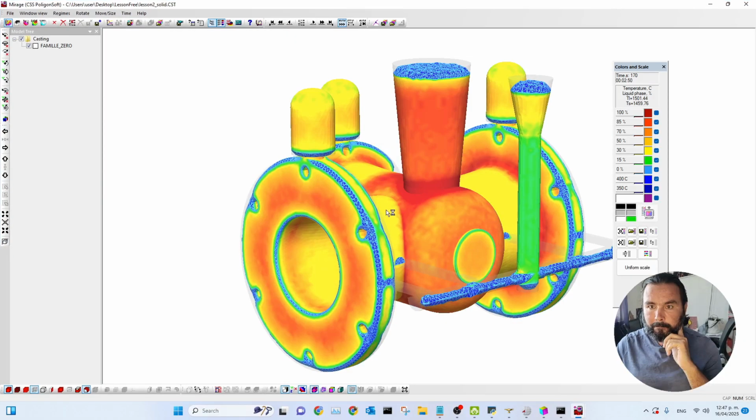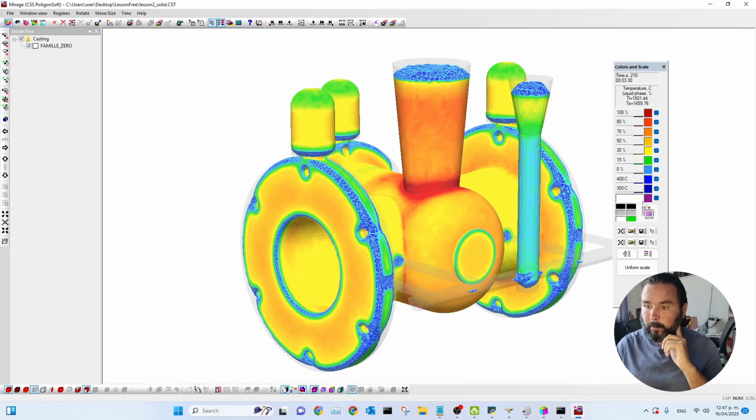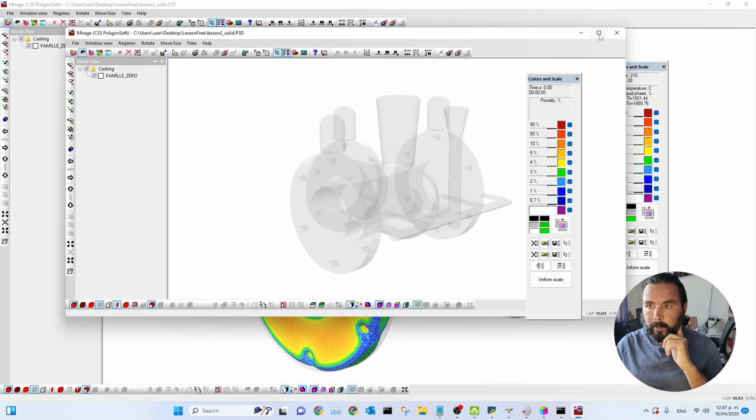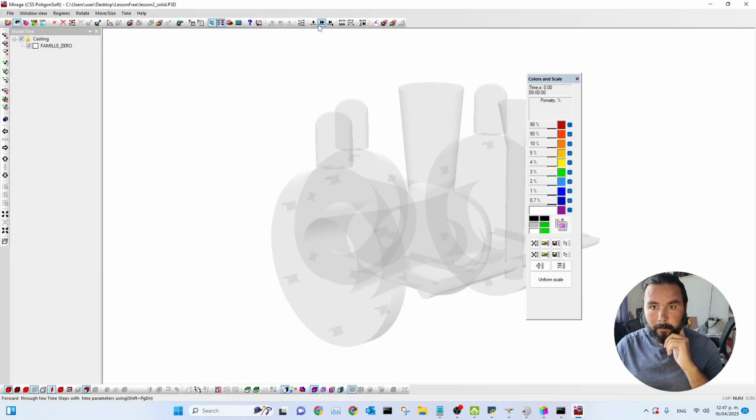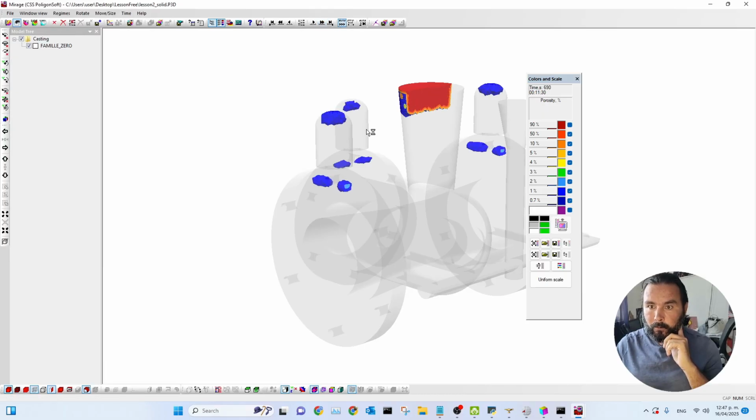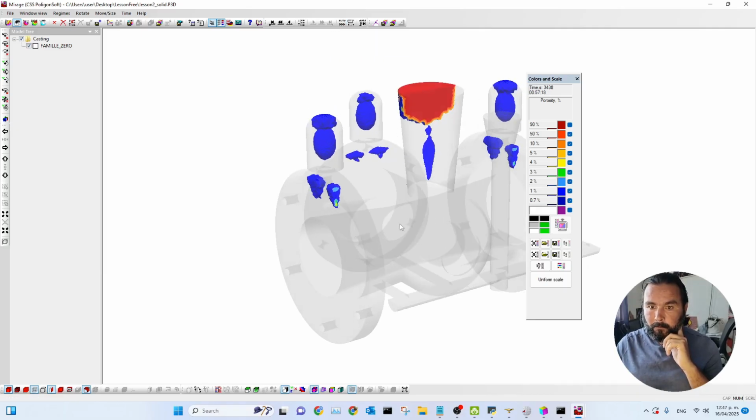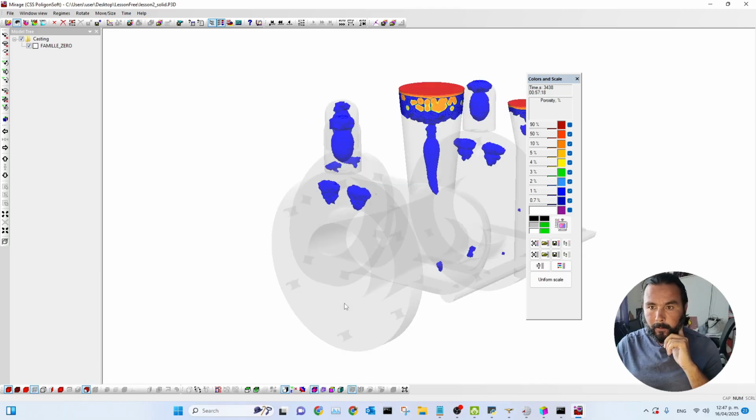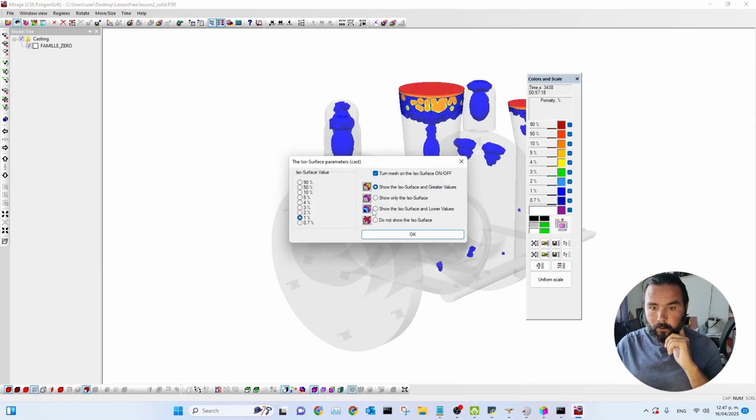First, let me turn off automatic playback. And I return to the porosities. I'll go quickly here as I'm not that interested in the dynamics. But anyway, we could also start the visualization to see how our porosities form. But really, in the case of porosity, I'm only interested in the image at the last step of the simulation. Here we can see the result, although I have the cut view turned on, the result with the isotherm for 1%.